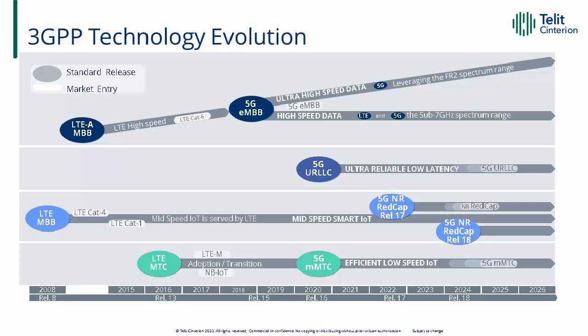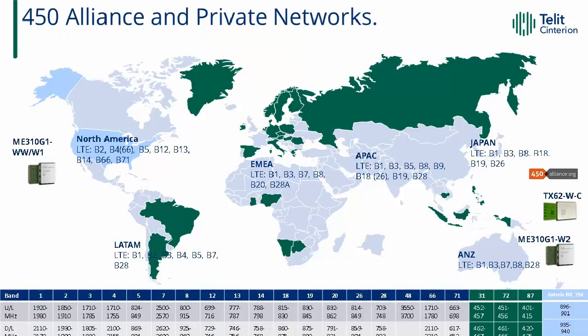And if we zoom into the LPWAN or MTC branch at the bottom, we see for practical reasons that actually lower bands are preferred, and the MTC branch is where most smart meters live, be it Cat-M for electricity or narrowband IoT, really suited towards water and gas meters. And this LPWAN or MTC, you can use the words interchangeably, technology is only really defined up to the lower mid-band.